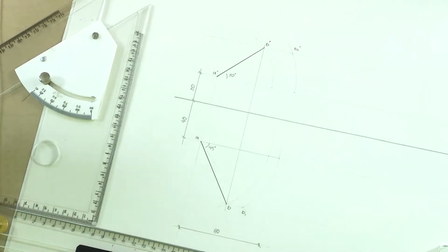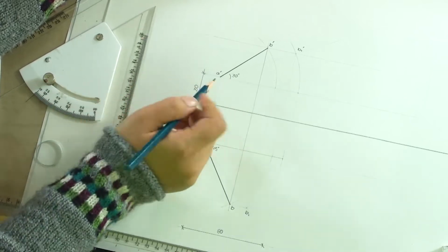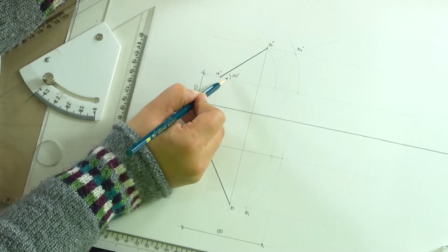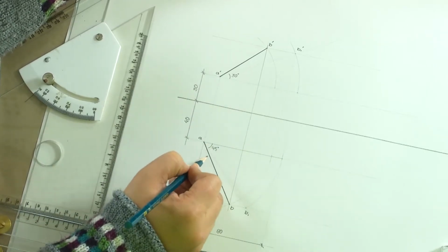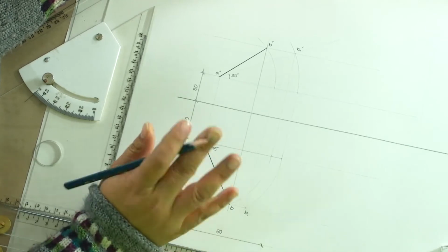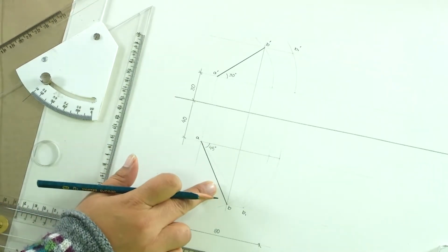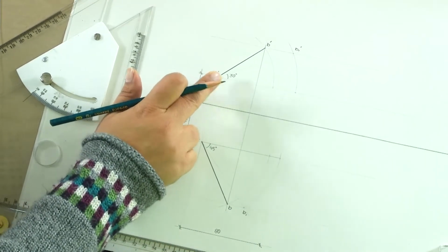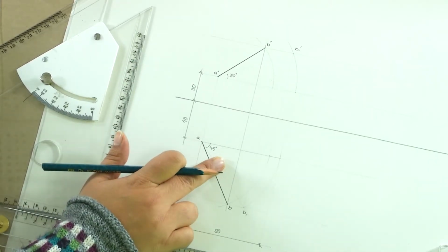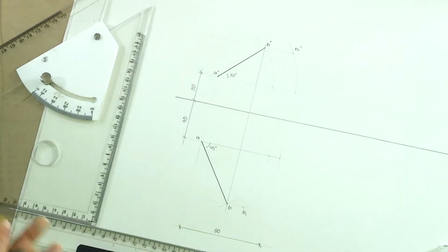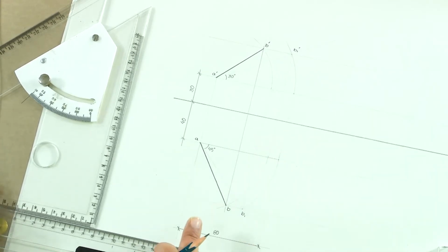Now, you can see very clearly that the actual angle of 30 degree is not the same angle that we see in the final projection. This angle has changed, and similarly this angle has changed from 45 to something else. We cannot determine that angle before we draw it. However, once we have drawn it, we can measure it, but there is no way to calculate it unless we do a detailed mathematical calculation. So, this is how we would be drawing the doubly inclined lines.